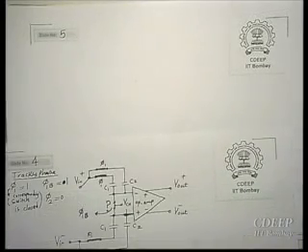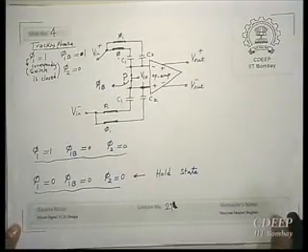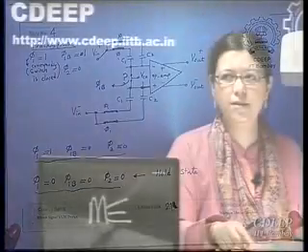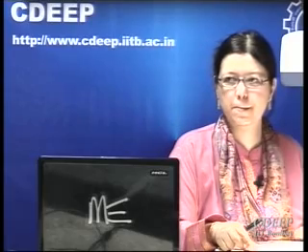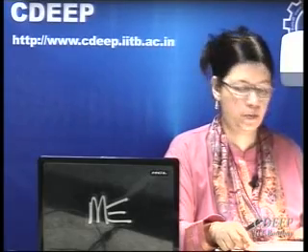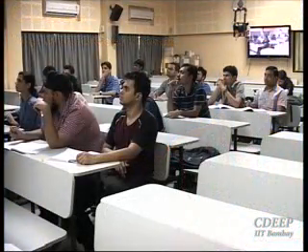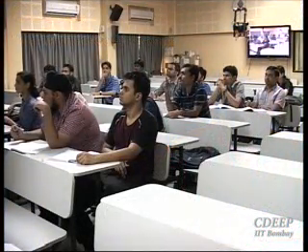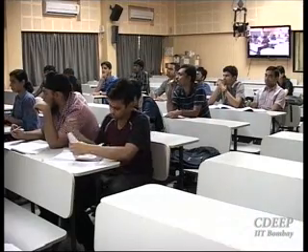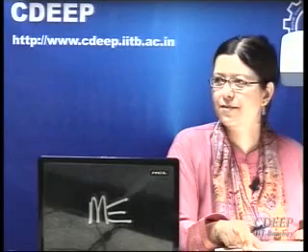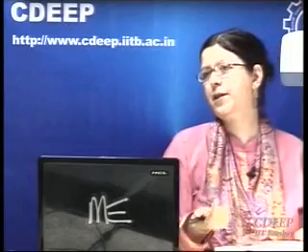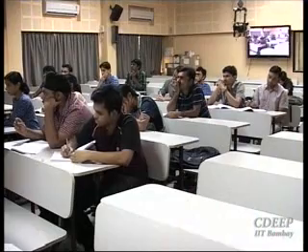Now we go with this state. So in this state, what should happen for C2? This is hold mode with gain. Phi 2 is used to generate hold mode. What should happen for C2? Then we will find the location of Phi 2. Yeah, C2 should be connected in feedback. Therefore, Phi 2 should be used to connect C2 in feedback mode. Yes. So C2 will be in feedback mode.